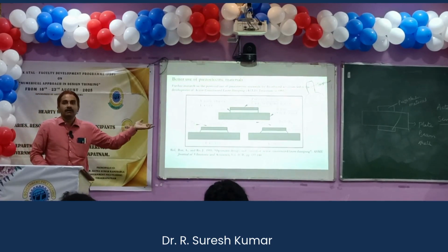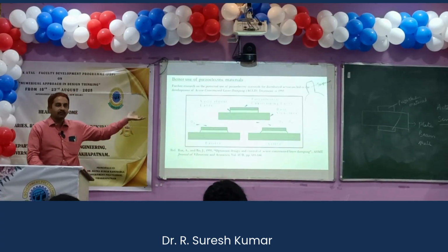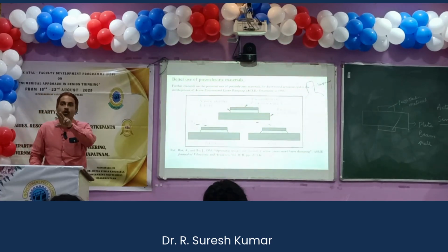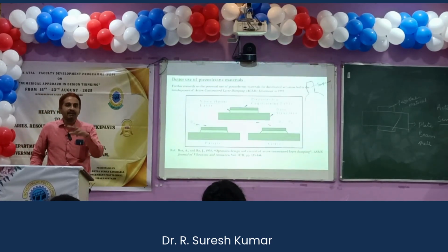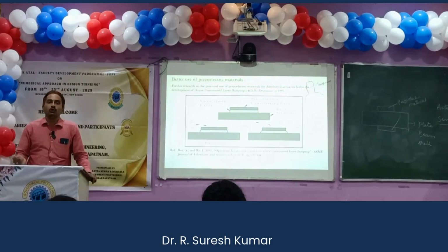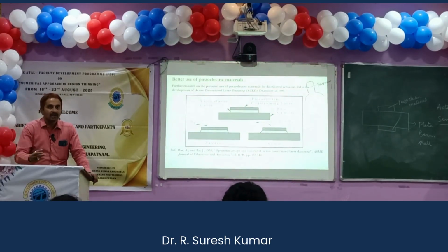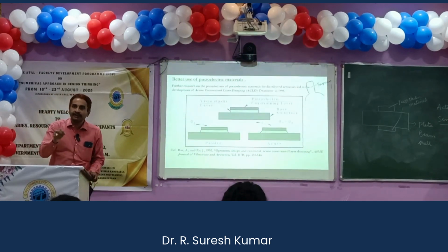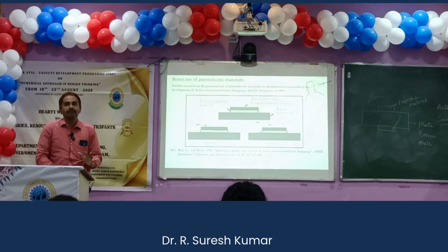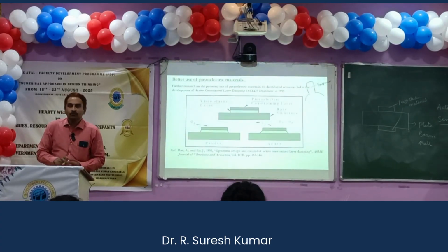The advantage of viscoelastic active constrained layer damping treatment is that it has both active and passive properties. What is passive? Even without giving any control voltage, it will damp some of the vibrations. But if you supply control voltage to it, the vibration damping will be very quick.